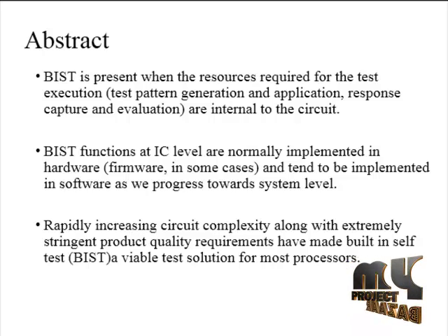This ultimately leads to an overall cost increase. In the 14nm Intel SoC, a reusable BIST engine called Converged Pattern Generator Checker (CPGC) is architected to detect memory and input-output defects and, combined with software-assisted repair technology, to automatically repair memory cells, including memory cell defects on 3D stacked wide input-output DRAM. Additionally, we also present the CPGC gate count, power, simulation and silicon results.